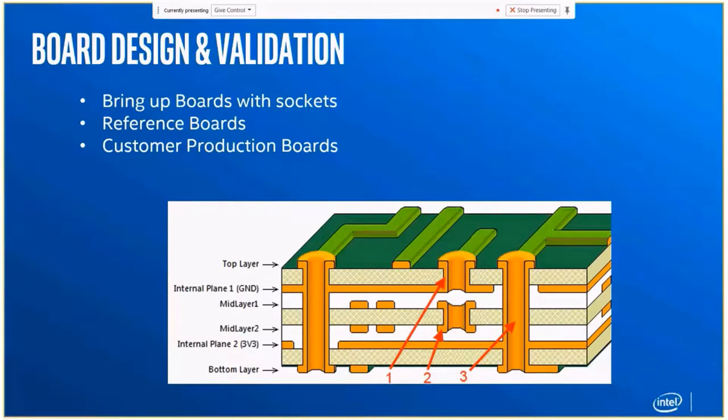The way it's usually done is using multiple layers of the board, right? Modern boards usually have like 17, 20 layers. So these are called vias. This is the top of the board surface, and these are actual connections coming in. You will have a drilled hole that has conducting material poured into it, and so this can connect this green line coming in to this layer, right? So this is a through via.